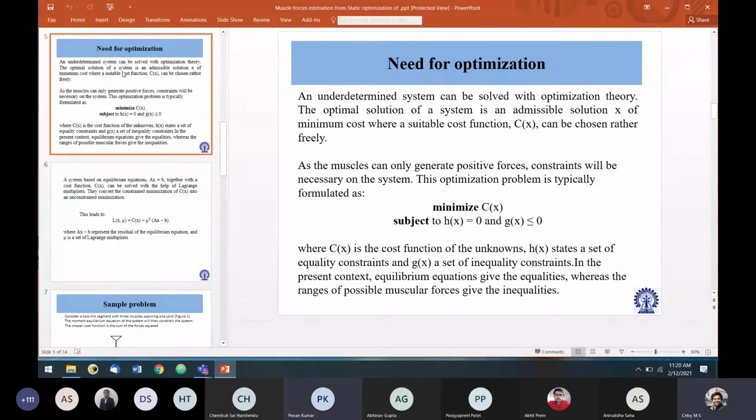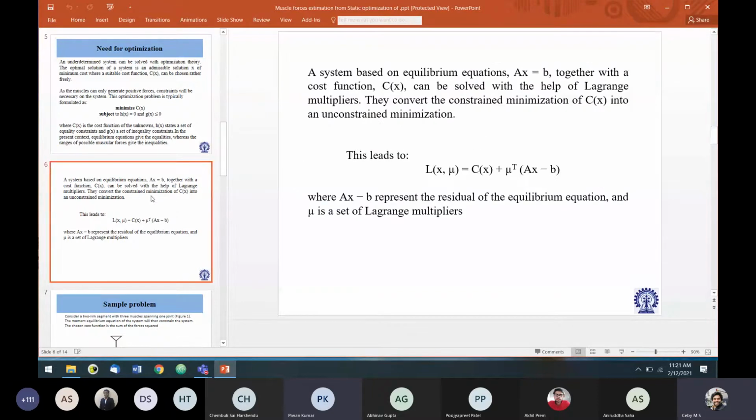Yes, sir. Hello. Yes, I can hear. So initially we have to use the main optimization function minus some Lagrange multiplier lambda times the equality constraint. Okay, yeah, so that is correct. We will have the main x variable vector, the design variable, and then lambda as another variable. Taking partial derivatives with respect to the x vector and lambda, we get n plus 1 equations you need to solve. That is perfect.